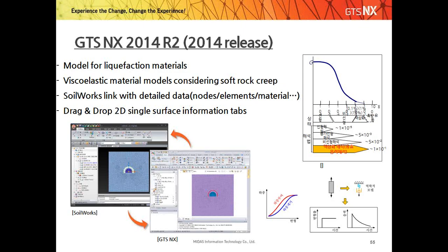From the LEM method we have the failure surfaces; it will define the arc failure surface where you expect the failure, because as you have already seen, in the SRM method we do not have well-defined failure surfaces. So in the SAM method we define the failure surfaces just as we do in the LEM method, but a stress analysis is simultaneously done, same as in the SRM method. So the advantage is that we have well-defined failure surfaces, as well as the stress condition in the soil for that particular model. So it's a combination of both, and it's very effective.